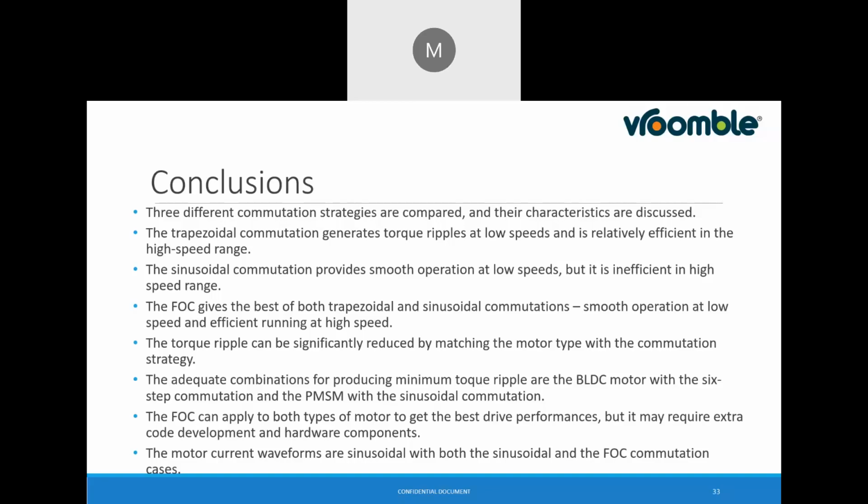And to energize three phase, I will need an AC supply. So in a BLDC motor also, I will use an inverter. So the operation looks like an AC motor. That was my basic question. It looks like an AC motor, now you understand why it is so? To control the speed, we require this inverter.